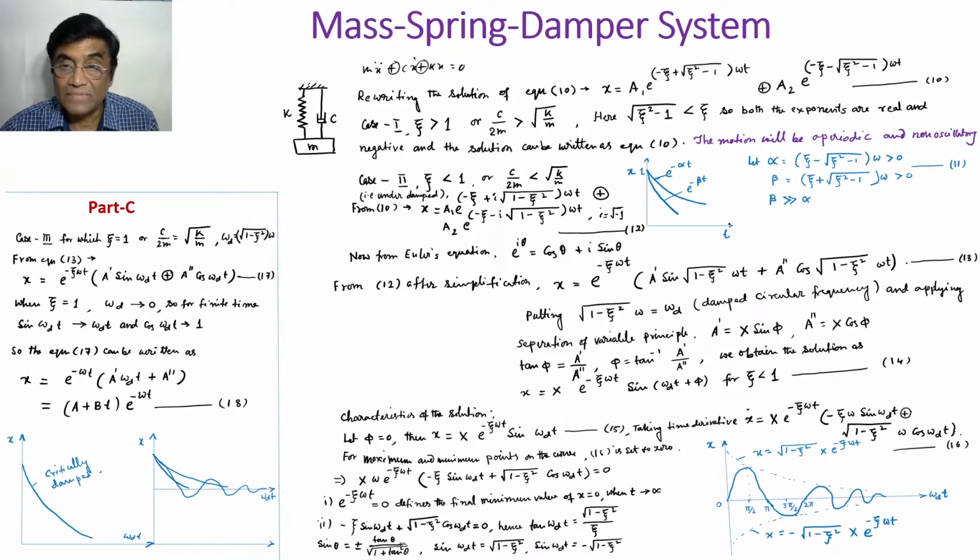That is called an underdamped system. And when zeta is less than 1, this becomes negative, so negative definite. That's why we introduced a term i, which equals root over of minus 1. And then I have written it like this for mathematical convenience. And then it can be proved that x will be oscillatory in nature.